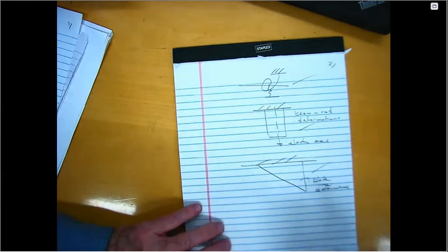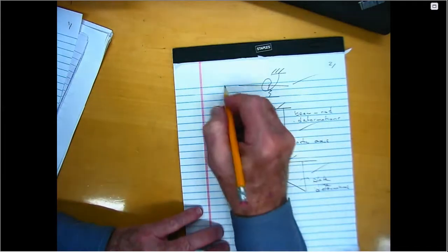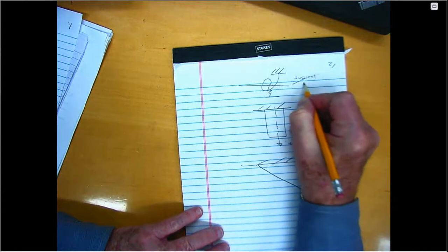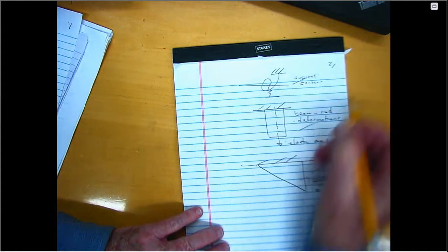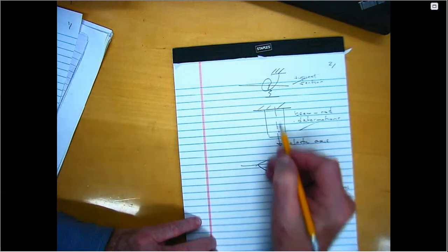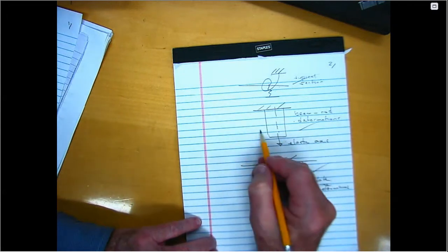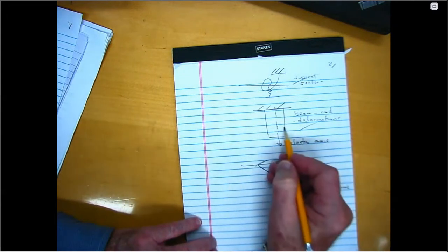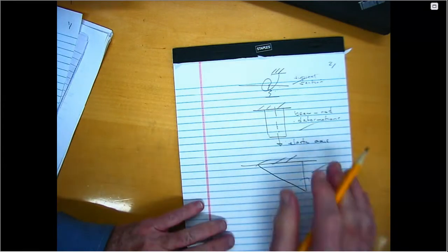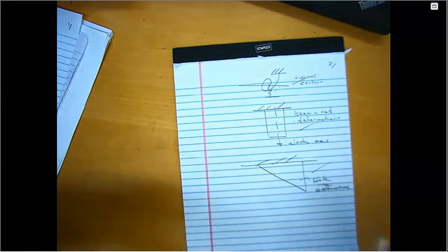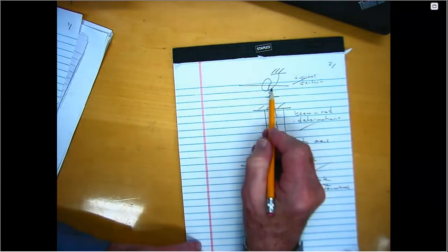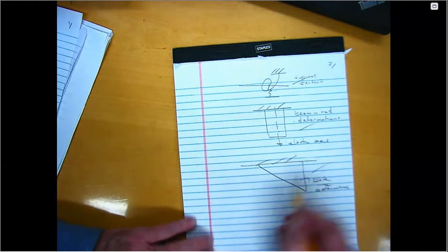Anyway, okay, so let's look at this one first. We'll call this the typical section model. By the way, it's called the typical section because people think of this as representing a choice of a section of this wing, and treating that section. We pretend there's some span-wise location that's typical of this wing, and this represents the dynamics of that section. Actually, that's not a really good way to think about it, but that is historically the thought process. If you really think about the fact that this only has 2 modes, the mathematics is pretty much the same. Okay, so let's look at the typical section model first.